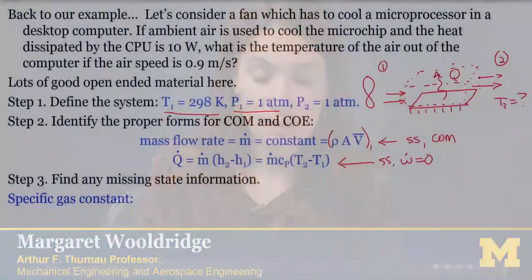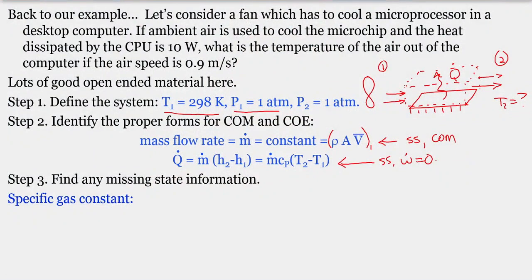Okay. So we solved the conservation of energy. We neglected kinetic and potential energy effects, and that gave us this simplified form of the conservation of energy. We took our solution for the mass flow rate and substituted that into the conservation of energy equation. And then we invoked an assumption of an ideal gas for air to allow us to substitute from the enthalpy to the difference in temperature times the specific heat at constant pressure. And remember, that C_P comes from the fact that we have enthalpies, right? That's the definition of enthalpy, and the specific heat at constant pressure.